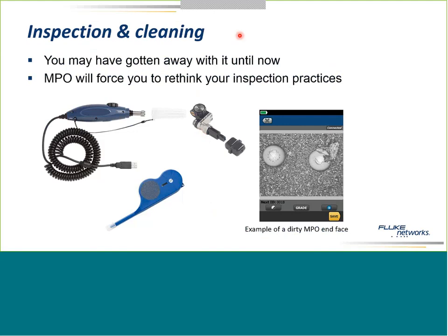Here we go. Now, as always, before I say cleaning and inspection, but better if it said inspection and cleaning. You don't always have to clean. Take a look at the connector. What's the condition? If it's clean, please don't rub a cleaning stick over it. Don't generate that static charge to attract some dust. But please do inspect your connectors.